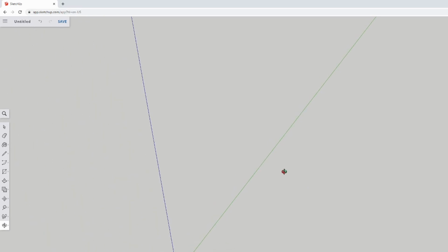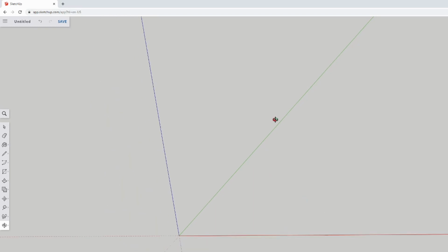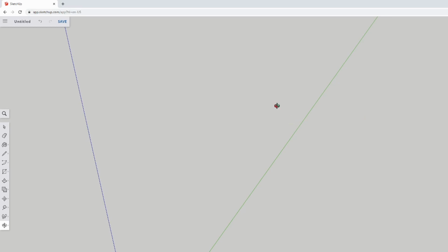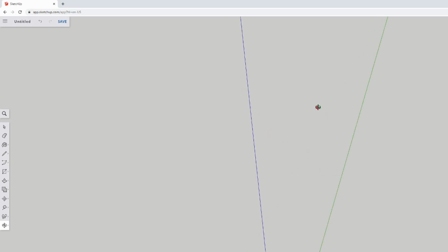You can use the scroll wheel to scroll in and out of the piece, and then wherever the mouse pointer is pointing, when you scroll in, it will actually shift and move the camera in that direction. So when I want to move around on a piece, I'll point in the area that I want to zoom in on. I'll scroll into that area, then in another position on the screen, I'll point and scroll out. And by doing this, I can kind of inch my way or wiggle my way across a piece, doing various zoom in and zoom out methodologies in order to do it.